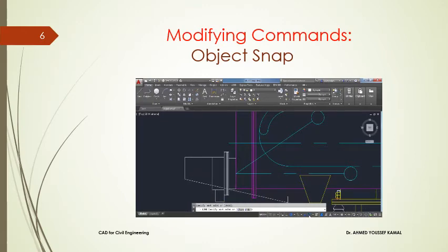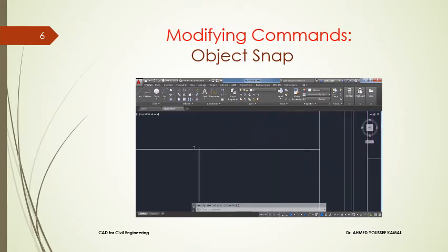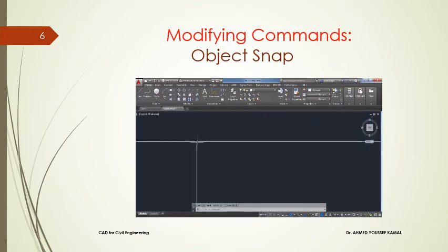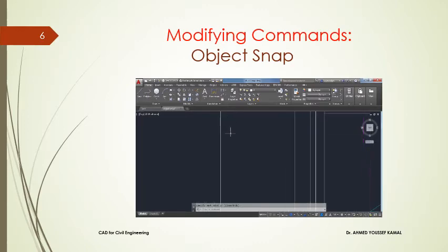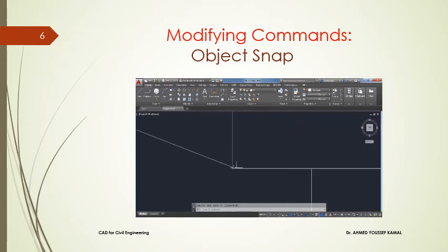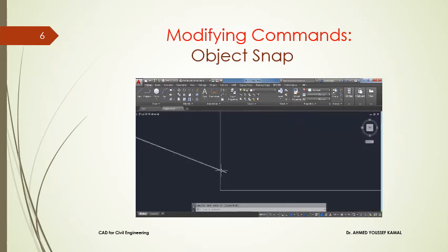Now let's go and turn this Object Snap off, and let's try to make a line that exactly fit at the intersection point of these two lines, and let's try to be as precise as possible, and now press enter. So in this case we have used Object Snap, but in this case Object Snap was not used. So let's zoom in. So when you zoom in, you'll find that this is exactly ending at the intersection of these two lines or at the end point of any of these lines which we have selected. But when you move your cursor to this one and when you zoom in further, you see that we are not exactly snapping it at the correct point. So this was the correct point, but it is not snapping. So in order to snap it to exact point, you need to keep Object Snap turned on.